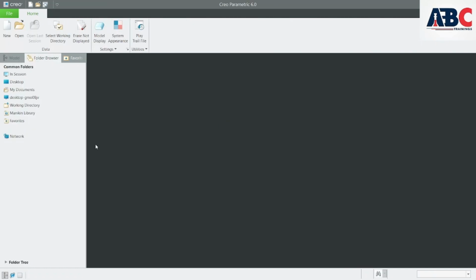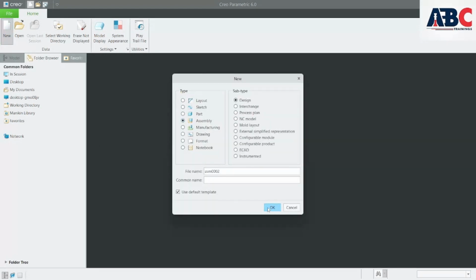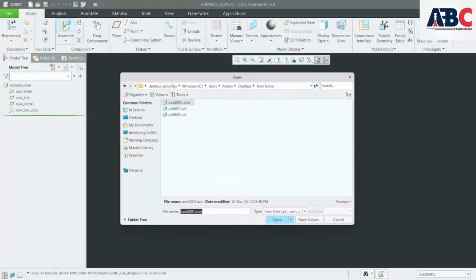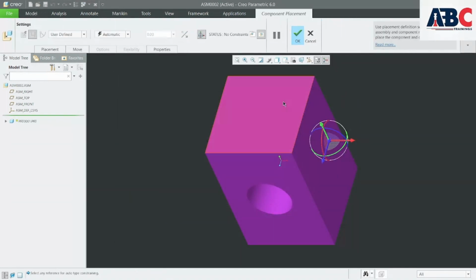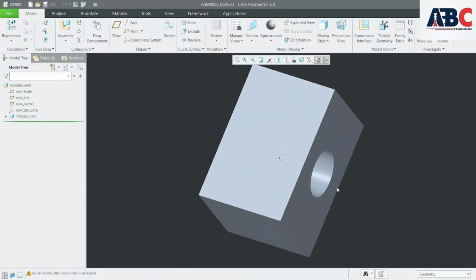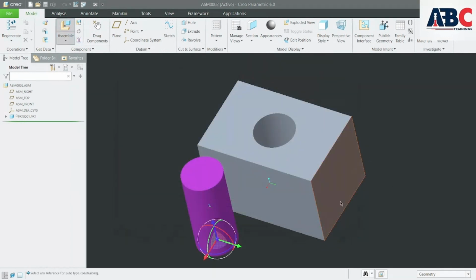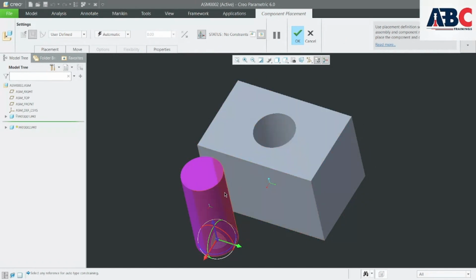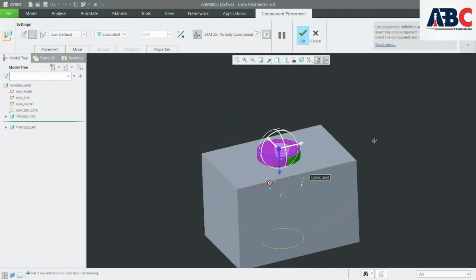Okay, now we are going to see the remaining part of this session, that is the exploded view. So let's go to new, go to assembly, click on OK, then assemble. Let's import these two parts here. This part, placement is okay, no issue. Then this part, click OK. You can directly give the constraint to this by selecting this surface. Automatic, that's why it automatically selects the constraint and makes it this surface. See, coincident, it has managed to assemble these two parts.